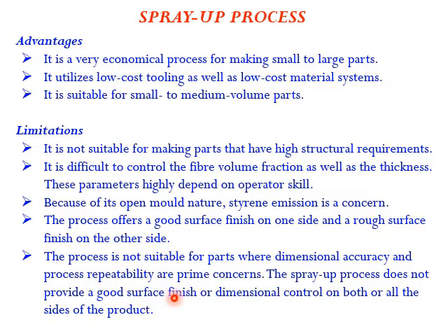The process is not suitable for parts where dimensional accuracy and process repeatability are a prime concern. This process is normally used where there are light load applications, like truck fairings, shower trays, bath tubs, caravan bodies, and boat hulls. In applications where there may not be any load bearing requirements, we go with this process.